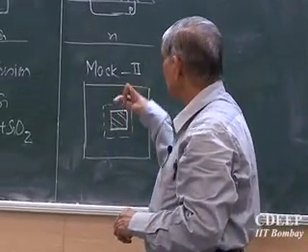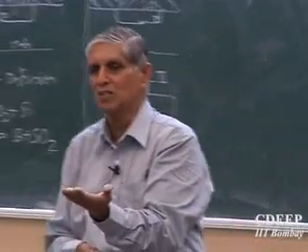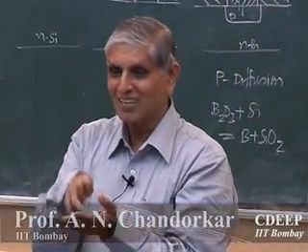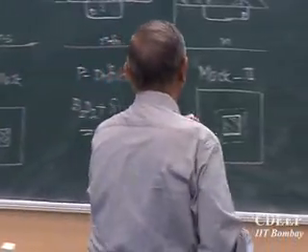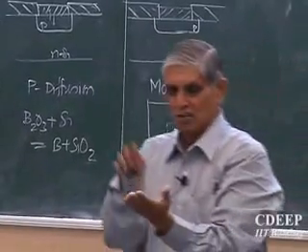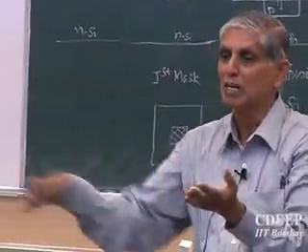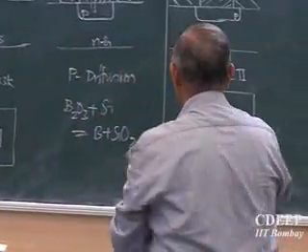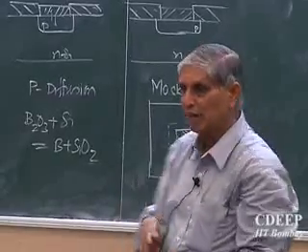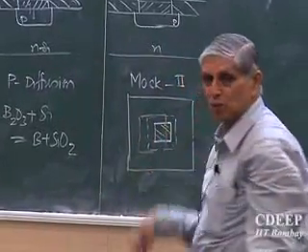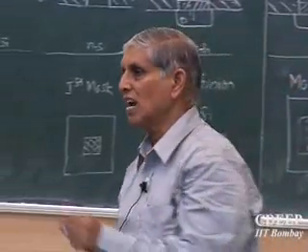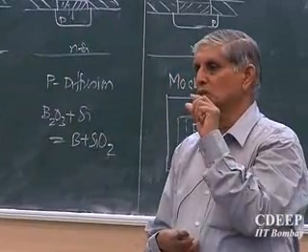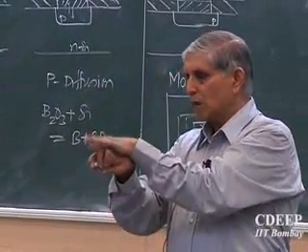The reason we keep this is that during the second mask printing, the first pattern is visible on the silicon because of the thickness change, and when I align the second mask, that window should actually get into the earlier window. So please remember, this window will be visible to me from the top. When I put the next mask, this is not one diode, there will be millions of diodes on the wafer. So everywhere this second window must get inside that. So I keep some leeway, otherwise during fixing, this may move. If they are equal, what can happen? I may get a pattern something like this, so I will have a smaller window on one side in some places. So I want to align, this is called alignment. The second mask is to be aligned with the first, therefore the size has to be slightly smaller, so that everywhere I can see the pattern inside.